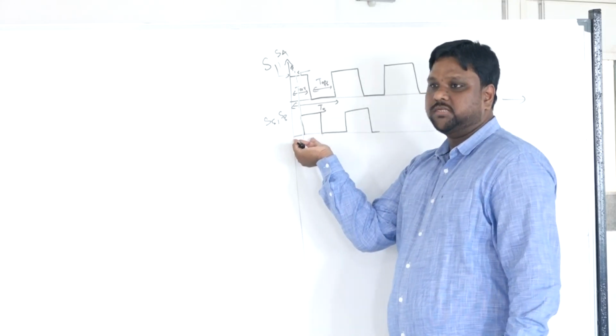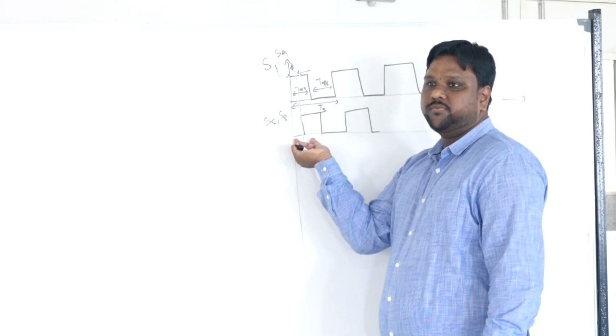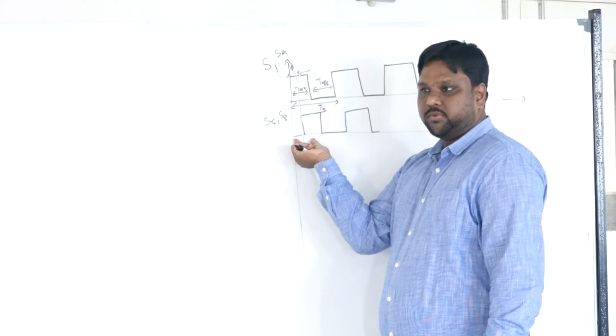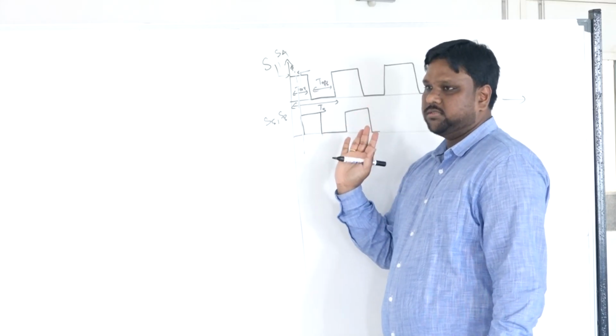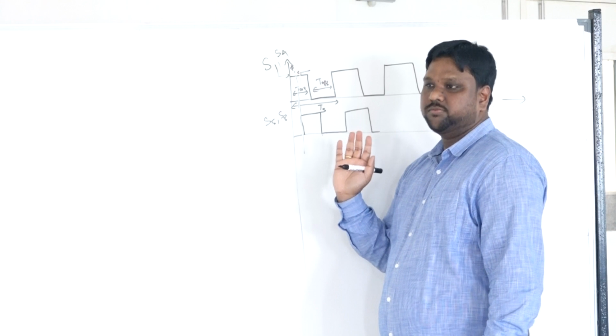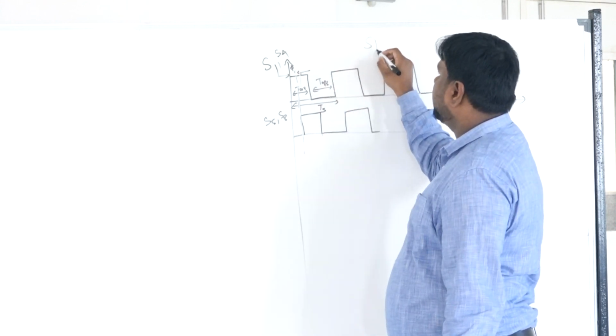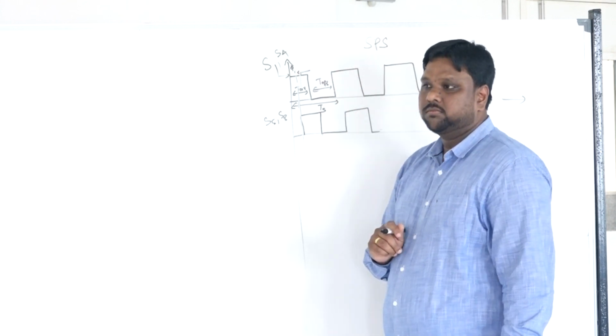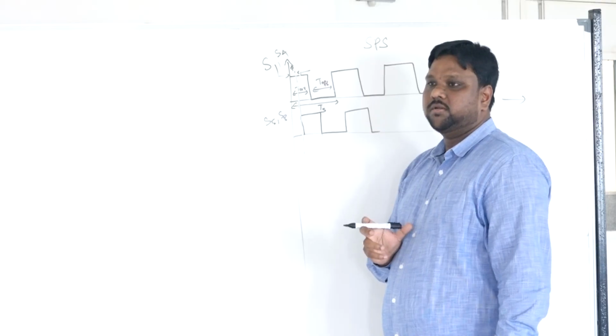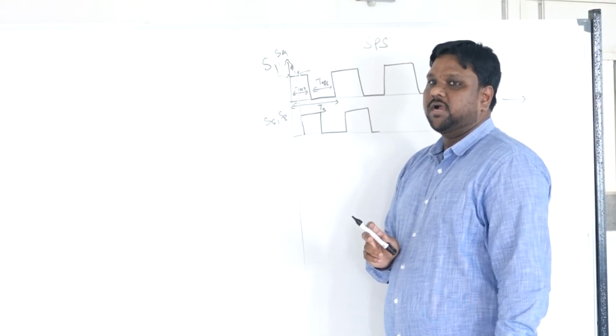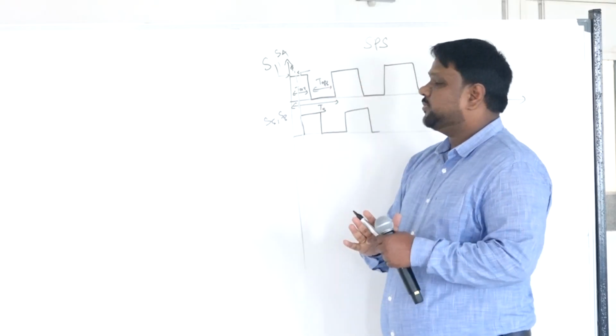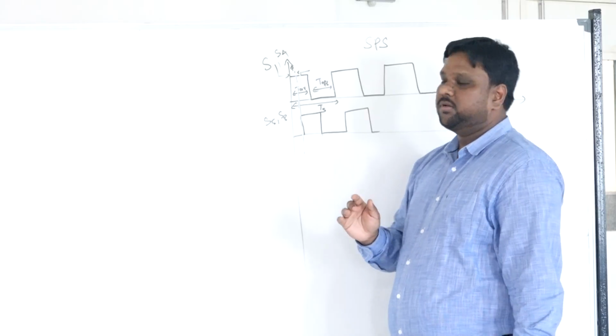The controller adjusts its phase shift instead of pulse width. No, pulse width we are not changing. Phase shift, this is called phase shift. Single phase shift modulation. The pulse width is not changed. We are only changing phi. I am just giving an example.